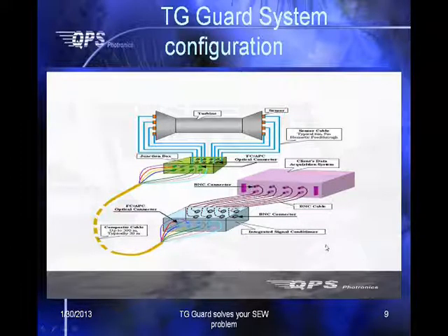So they will unfortunately be plagued with problems. Sometimes the signal will come with a lot of noise, and if you don't have access to the original time domain raw data, you might conclude that you have very large RMS vibration or peak to peak. It can be fictitious.